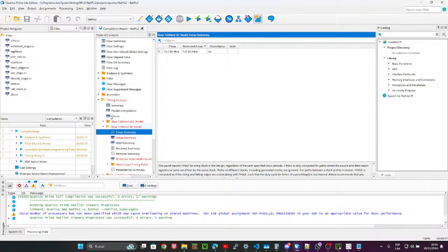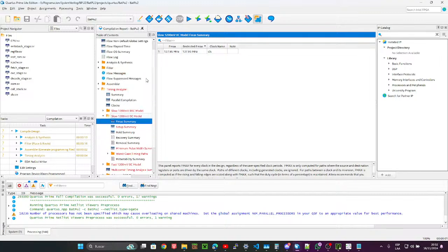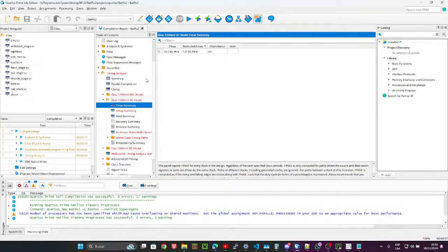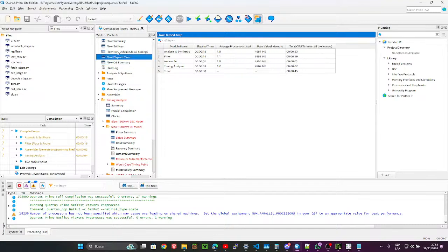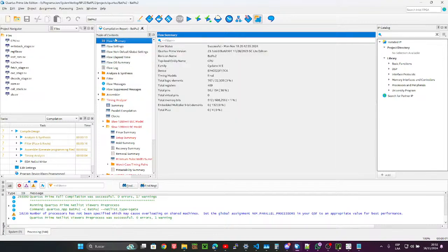It's there for a reference, and then what you do is, the PLLs on the FPGA actually have two dividers. It's the divider for the feedback and the divider for the output. And so essentially you can say, give it 1 megahertz input, and then say divide by 3 for the feedback, right? Divide by 3. And that causes the PLL itself inside the oscillator to output 3 megahertz. And then you set the other divider to 2, and that causes essentially 3 divided by 2 scale on the 1 megahertz, and you get a 1.5 out.